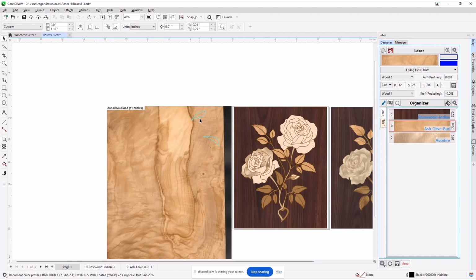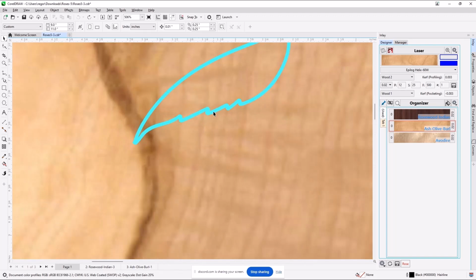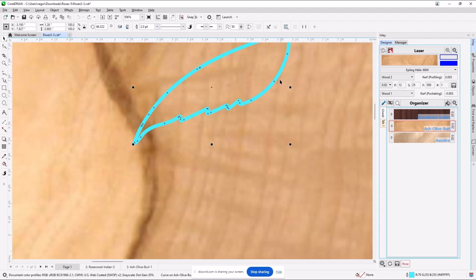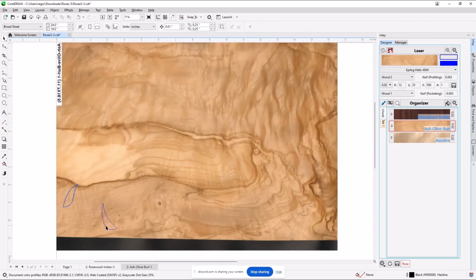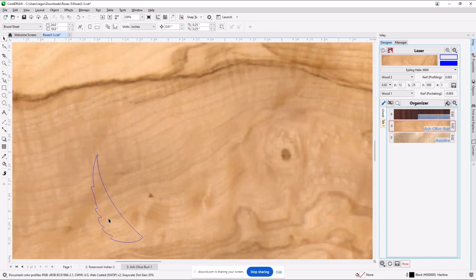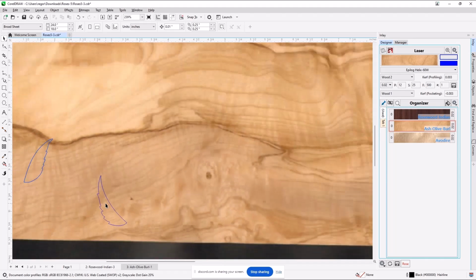That's what the kerf collection does. If you zoom in on this, the difference is that this object with the extra points, we're literally going to cut on a pocket, the inside dimension, or we're going to cut on the outside dimension so that when the laser does the cut, the edge that actually comes up on the veneer piece follows the center line here. So what Vincent has done is basically corrected for the kerf by choosing the outline here that is just a smidge larger than the piece on the picture. So once it's cut, it actually fits that interior piece and will butt up to the next one with no kerf.